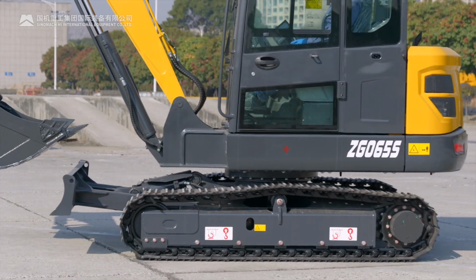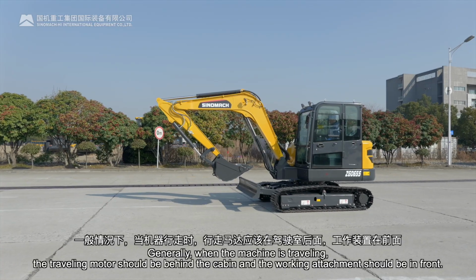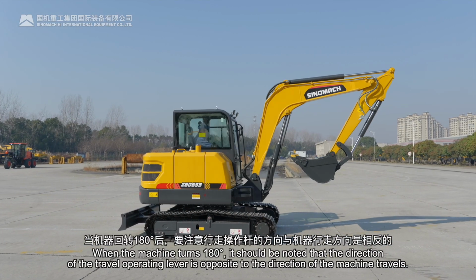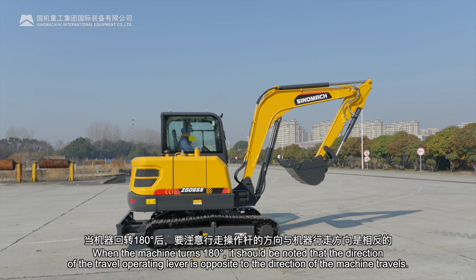Machine travel. Generally, when the machine is traveling, the traveling motor should be behind the cabin and the working attachment should be in front. When the machine turns 180 degrees, it should be noted that the direction of the travel operating lever is opposite to the direction the machine travels.